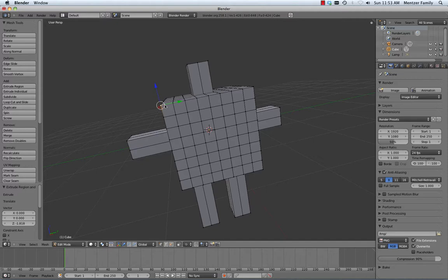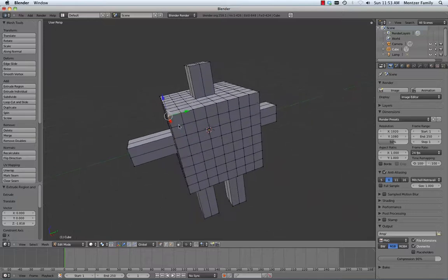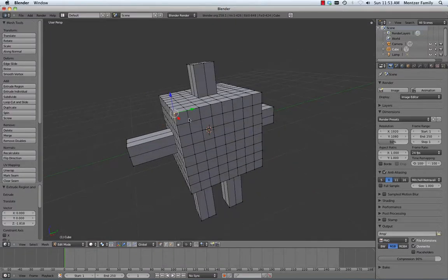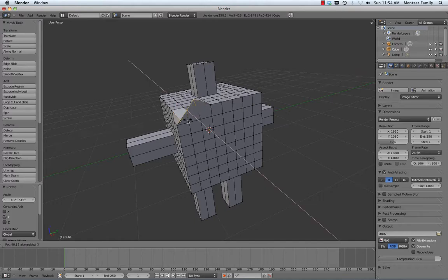And sometimes when you're doing rotations especially, it's really nice to limit yourself to a specific axis. You can do that by just hitting X or Y or Z when you're doing that. I'm going to rotate and say I want that to happen only around, for example, the Y-axis. And then that vertex now is only spinning around the Y-axis. We couldn't see a whole lot happening there, but let's grab a few so that we can actually see that rotation taking place. So again, R to rotate, and then let's limit it around the Y, and let's try the X-axis. There we go. That lets us actually see. So we're locked right now. We're constrained into spinning or rotating these vertices only around that one axis.